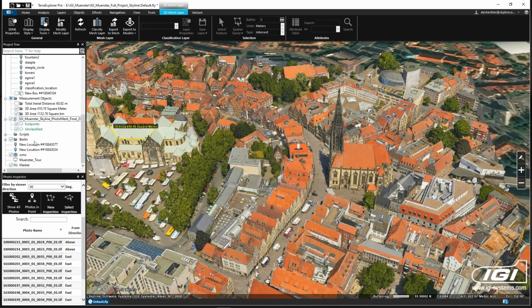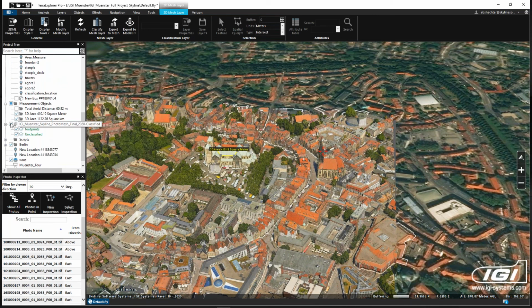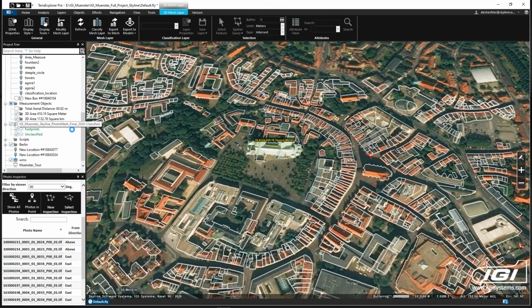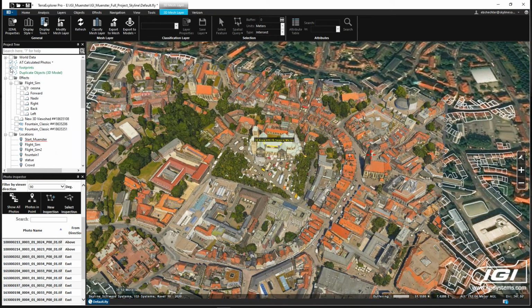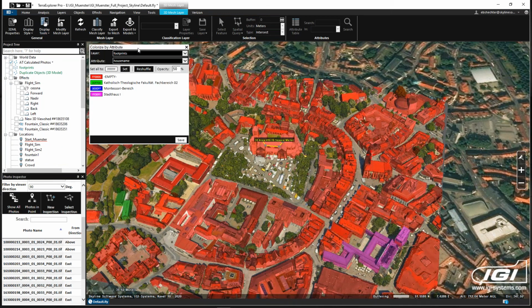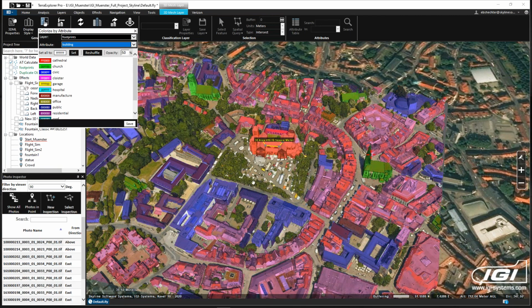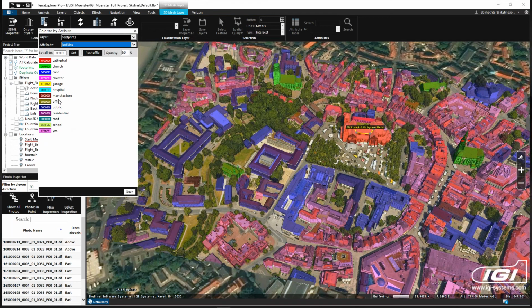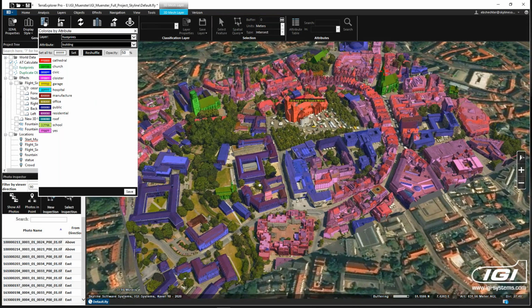Additionally, the data can have incorporated classification. So if you have GIS data such as footprints, you can see this is the footprint data for this area, just a 2D footprint, but it could also have a 3D component such as the height. That could be embedded dynamically into the mesh so that I could then colorize the mesh or query it based on attributes. You see, these are the different buildings, and you can also create your own legend based on how you want to colorize it. And then you can also query it.